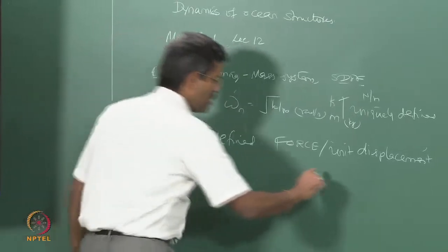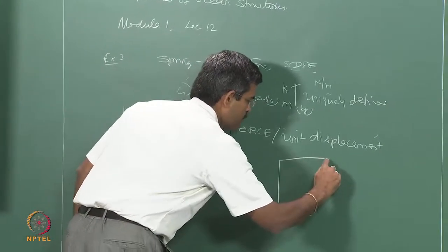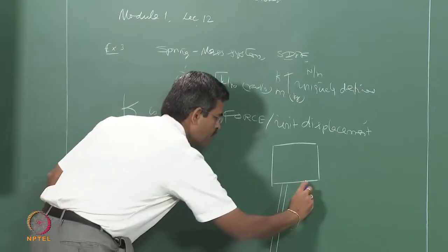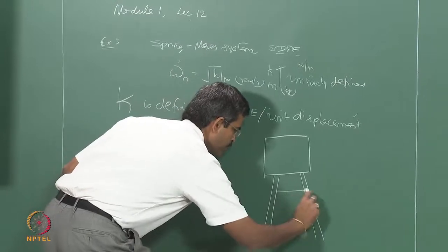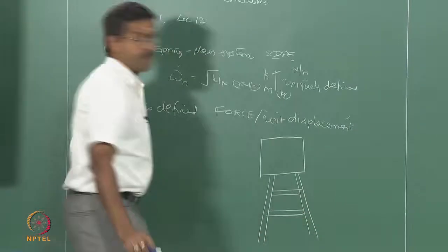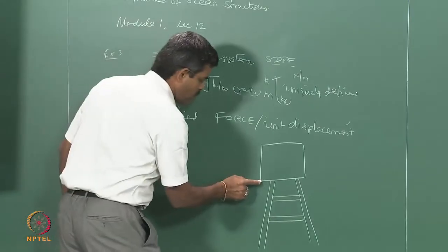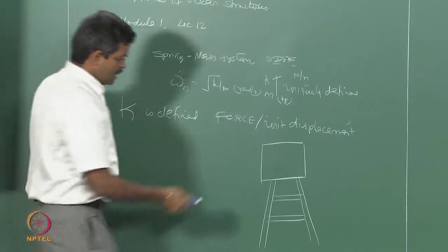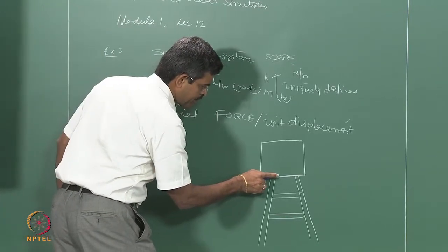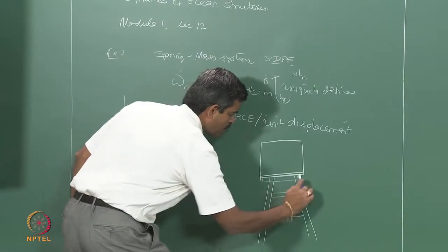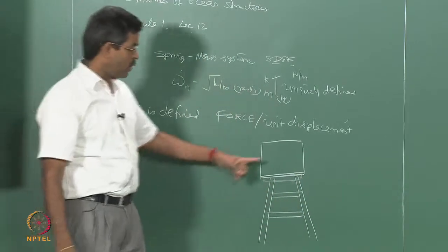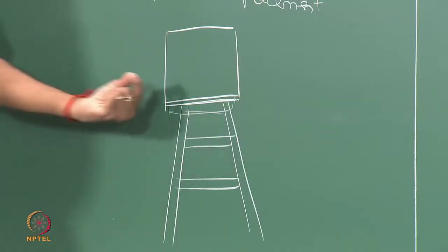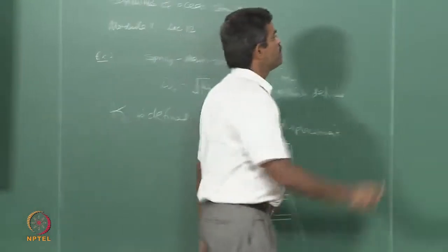So, we all know that, let us say if I have an offshore platform, maybe even a jacket, is a template structure. We all know, as a structural engineer or a person who understands strength of materials, that if, for example, there is going to be a deck here, the deck needs a support system which will transfer the load from the top side to the ground or to the support system. Let us talk about this particular system, which is a typical